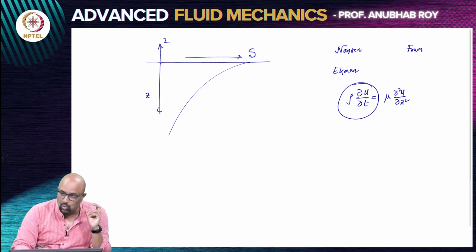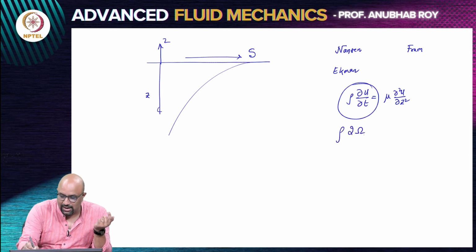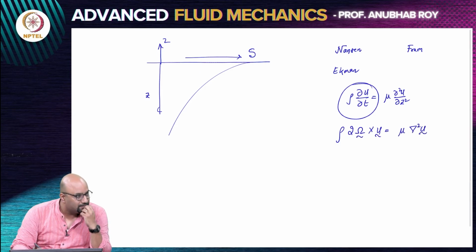What matters is you are solving fluid mechanics on a rotating background. So, there is Coriolis acceleration which is important. And so, instead, the governing equation is this. You don't have unsteady acceleration, you rather have Coriolis acceleration.